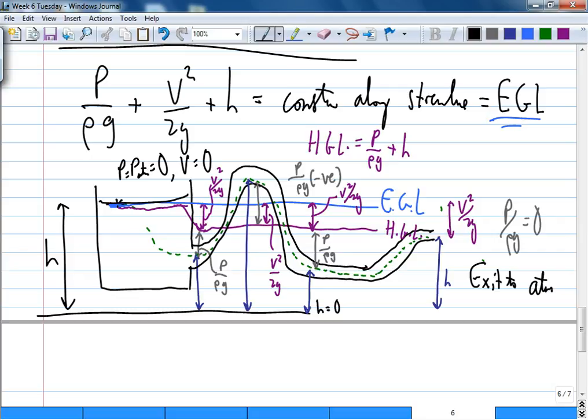So the pipe cannot exit down there. If I exit down there, then the system is not in equilibrium. The pipe must exit basically at the HGL like that, because the atmospheric pressure should be 0 at that point. Is that okay?